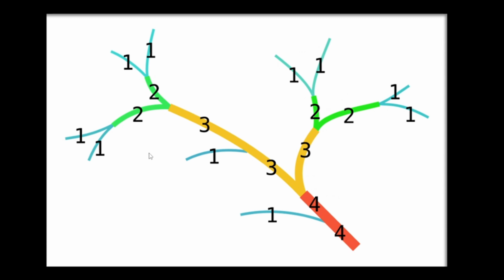Strahler Order is assigning numbers to streams based on their order. So the first order has the lowest stream value, and two streams of the same order joining at the same point give a higher order.